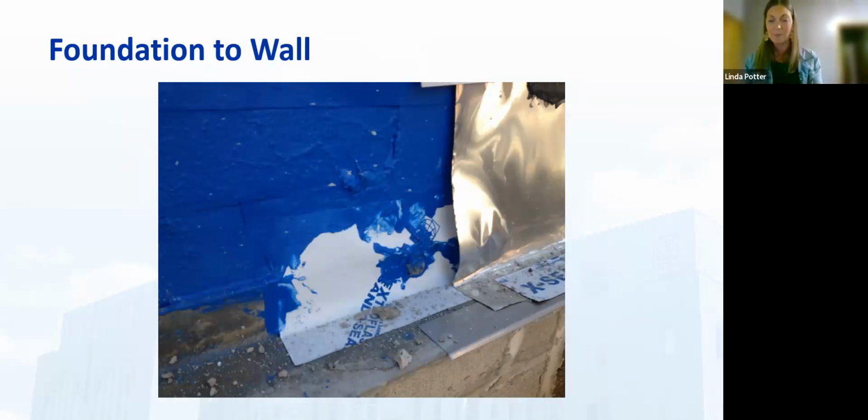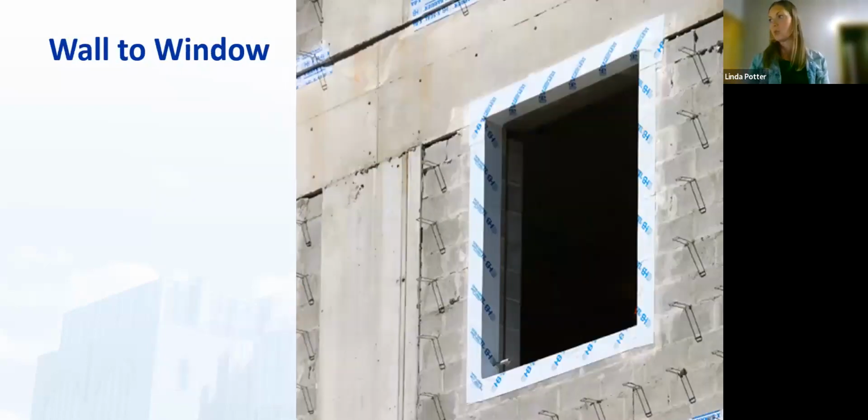Who's responsible for that? Walls to windows, we're going to want to see that those openings are handled. And some of this gets tricky when you're looking at mass walls or using brick in front of block, or brick in front of anything, because we talk about flashing, that's through-wall flashing, which is completely different than opening flashings for air barrier systems.